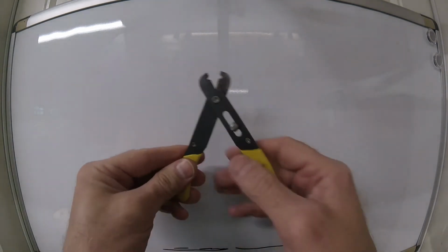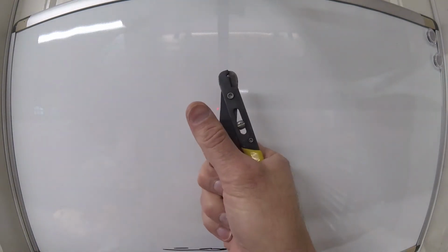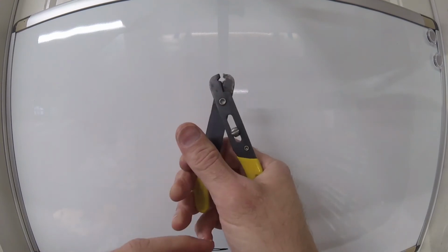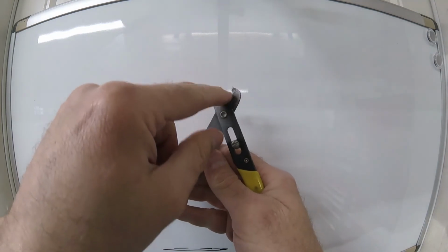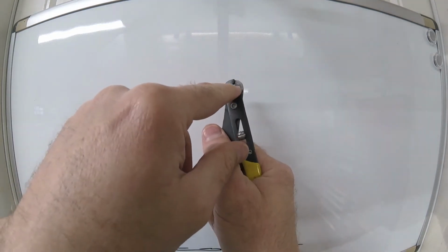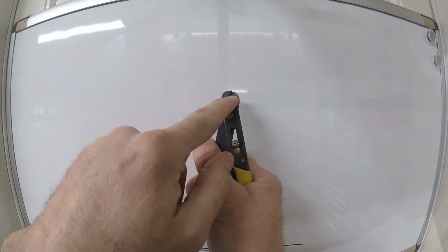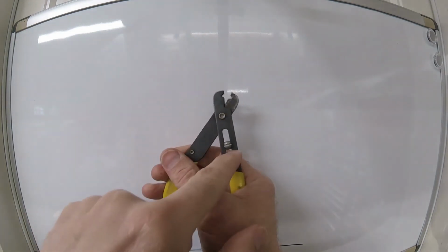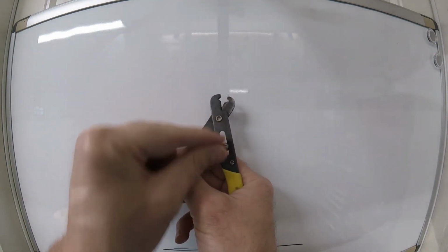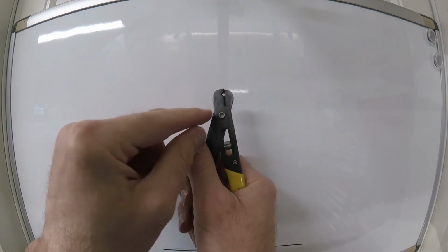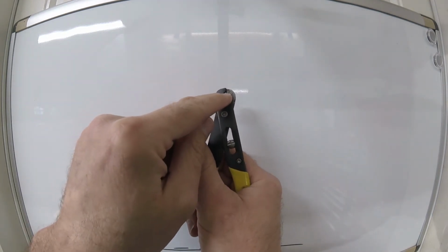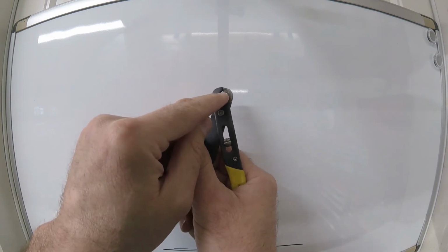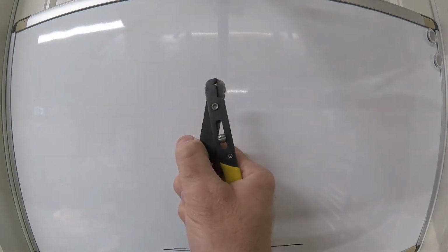Here's another tool. This is specifically for stripping wires, and for this one it just has one stripper section. It does have a cutting section back here, but you notice up in there the hole gets pretty tiny. If you need to adjust that, you loosen this screw and move it up and down in the slot until it stops the jaws from closing any bigger or any smaller than you want. Because you don't want the jaws to close too small on your wire.